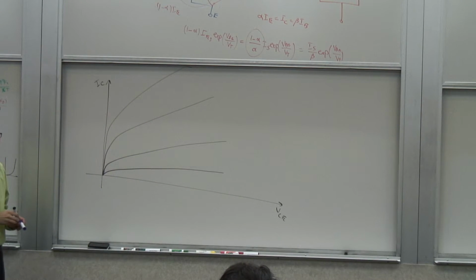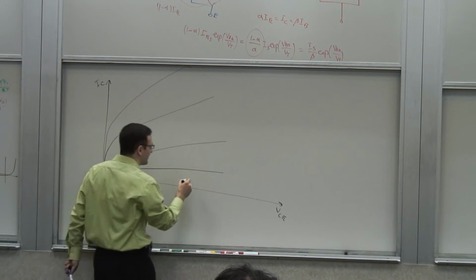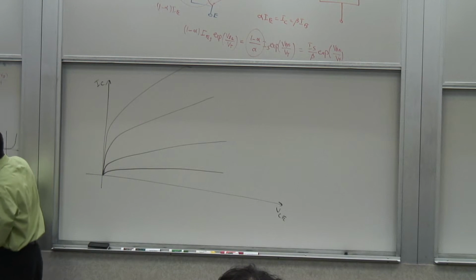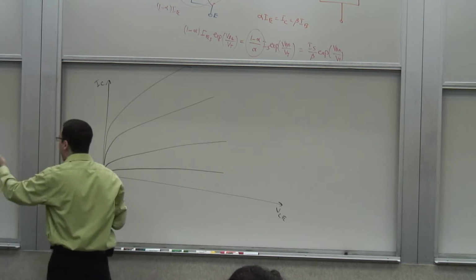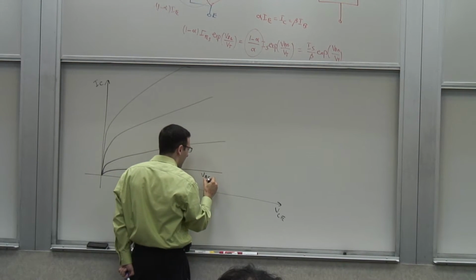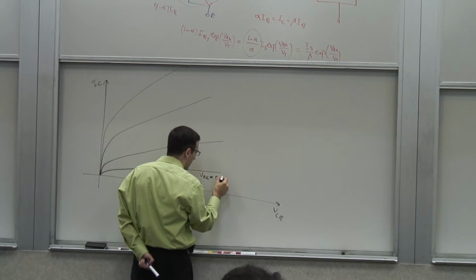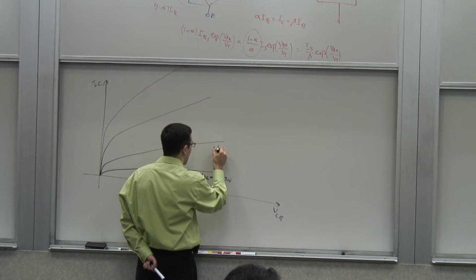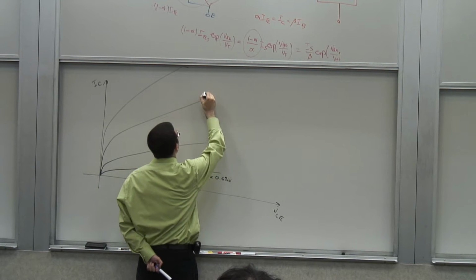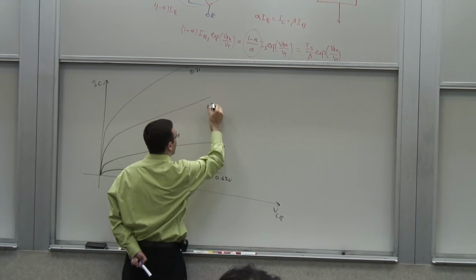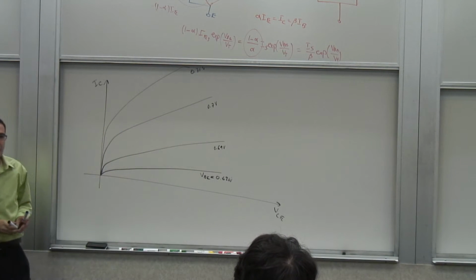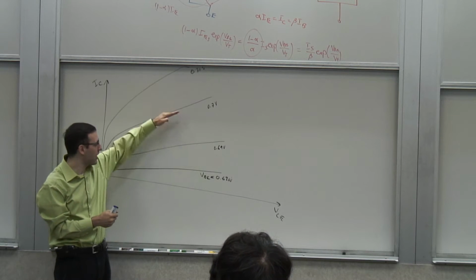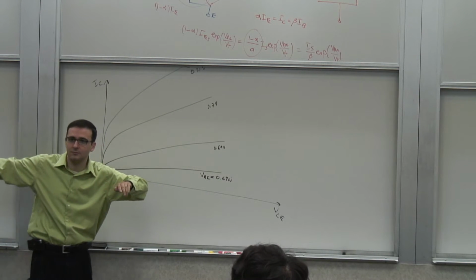VBE. This is very sensitive because it's an exponential. This is that exponential that we had here. So this is, for instance, for VBE of just maybe some hypothetical number, 0.68 volt, 0.69 volt, 0.7, 0.71, something like that. Of course, I'm just trying to emphasize how sensitive it is. This slight change in the VBE creates a major change in the current because it's an exponential dependence, right?